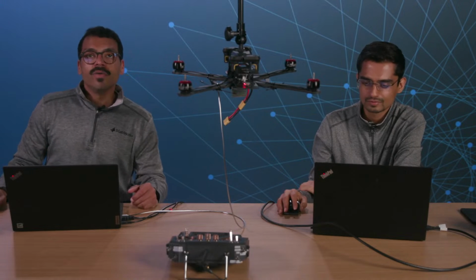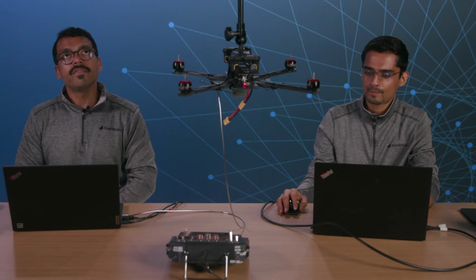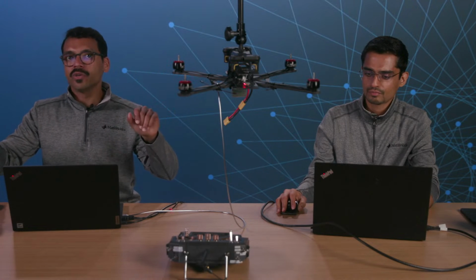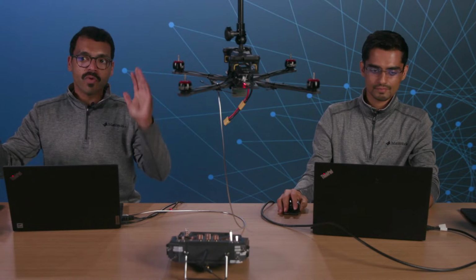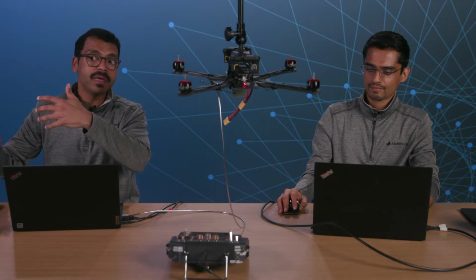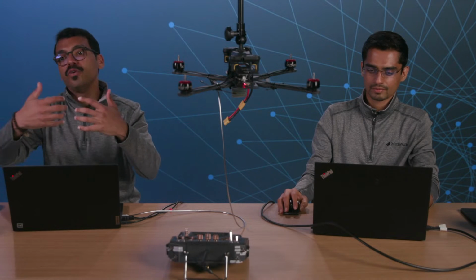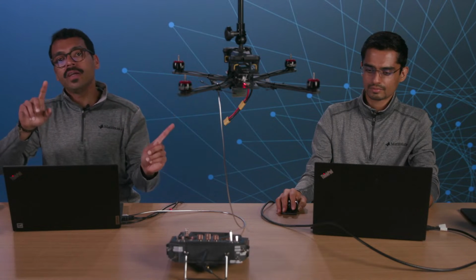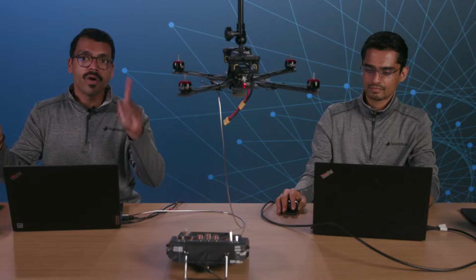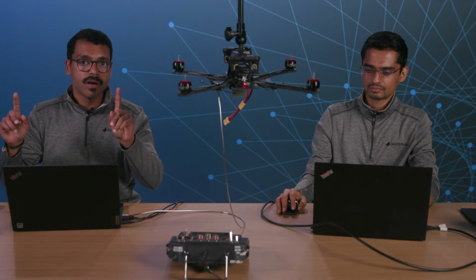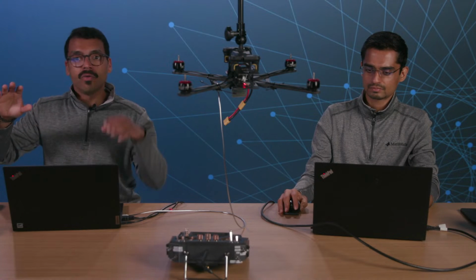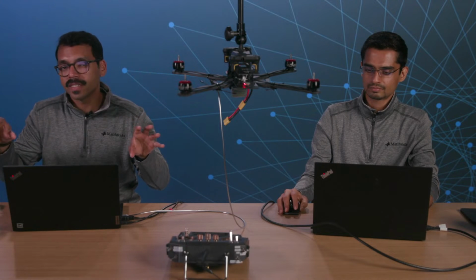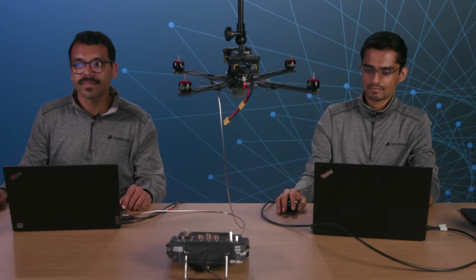Oh, that's really cool. So if you have Simulink, you would have Simulink on both of them. So what you would do is, from one Simulink, you would send out a UDP message, and on the other Simulink, you would read a UDP or TCP/IP, just any network protocol. You'd be communicating over from one PC to the other using a network protocol, and on one you will have your platform dynamics, on the other you'll have the simulation piece. But yes, you can.